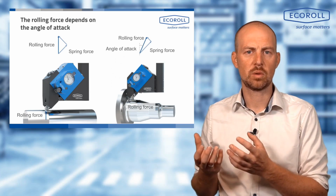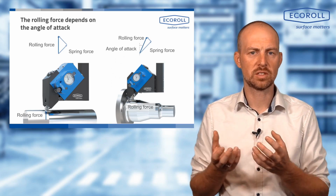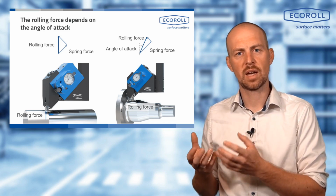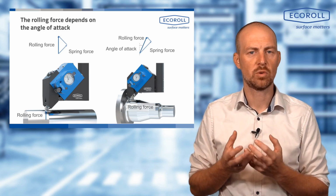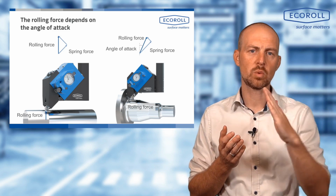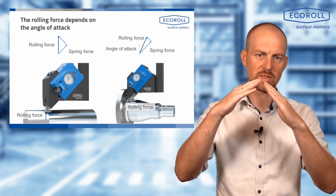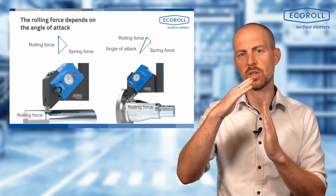So now, when I define my rolling force for a process, and I have simulated the whole thing, I have tested it on cylindrical components. Then of course, I have to try to achieve the required rolling force in the curved arch. And for that, I need to know that this rolling force changes depending on what my angle of attack is. Because of course, this rolling roller is positioned at the appropriate angle to the springs, and the angle of force application is then designed accordingly.